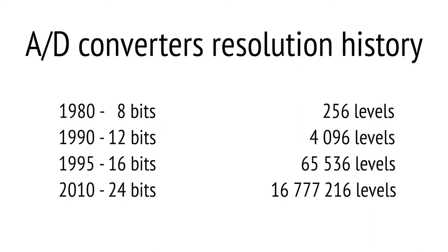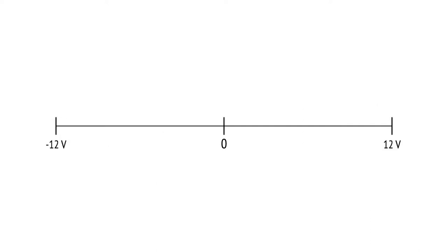What are the consequences in practice? We talked about the voltage range plus minus 12 volts, which enables us to measure 120 G's peak. The sensor sensitivity is 100 millivolts per G. If we use a sensor with 10 millivolts per G sensitivity, then we can measure 1200 G's peak. The plus-minus 12 volts range looks optimal.